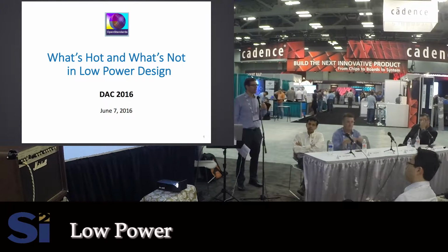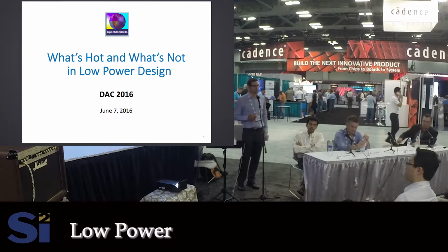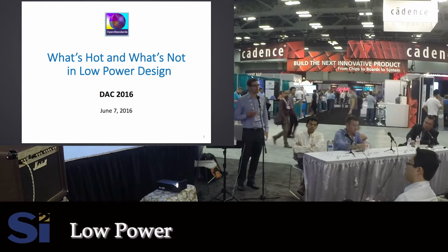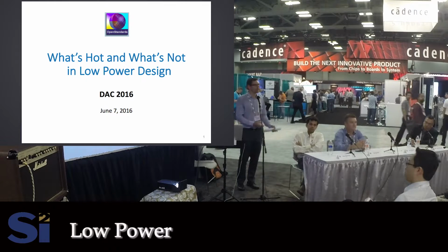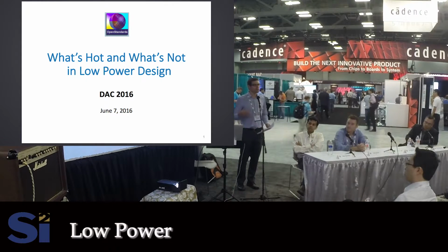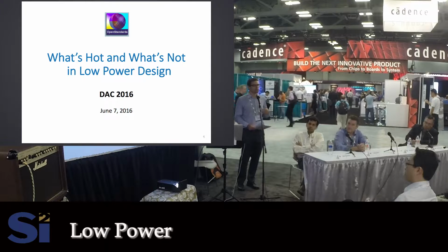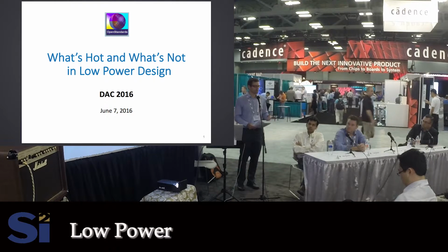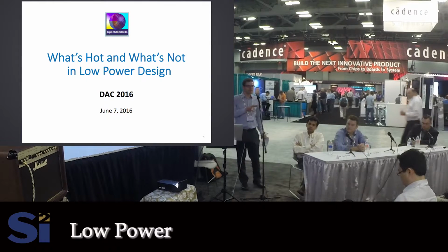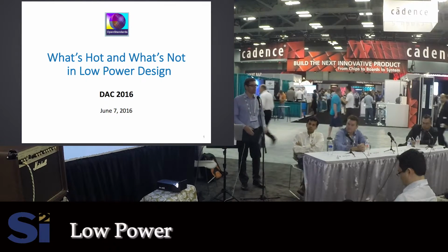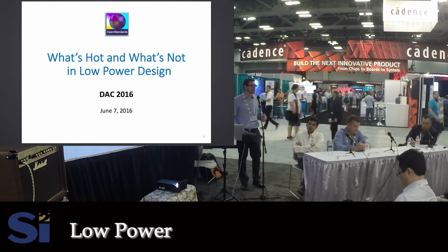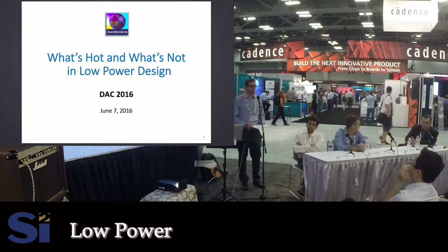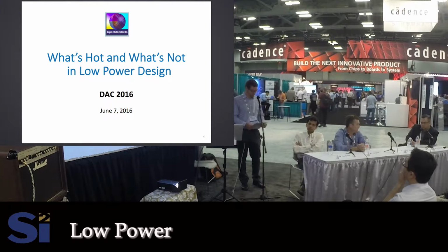It's very similar today, as what we're developing for our blocks is a power recipe. Instead of spending that effort on timing, now we're spending it on power. How can we reduce power in our blocks? Each block has a different recipe, maybe a different clock gating style. Maybe some blocks do well with sequential clock gating. Maybe some do well with hierarchical clock gating or multi-stage clock gating. So we're really focusing our efforts now on power instead of timing. And that's one discipline, silicon implementation, but I also see it in architecture, verification, design, RTL development, etc., where we're really focused more on power.